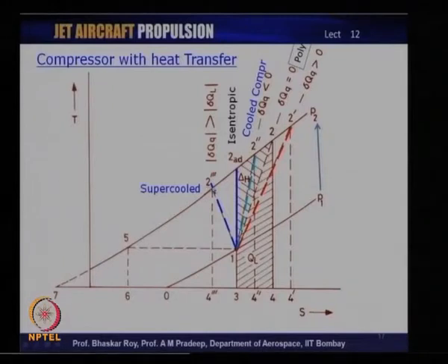So, the pressurization would indeed be achieved, but you would arrive at a temperature of a lower value at the end of the compression process, even lower than the ideal. For a jet engine, that may not be a very desirable situation, because the flow from the compressor is going to the combustion chamber, and a supercooled flow going into the combustion chamber would require additional heating for the flow to be taken to high temperature.